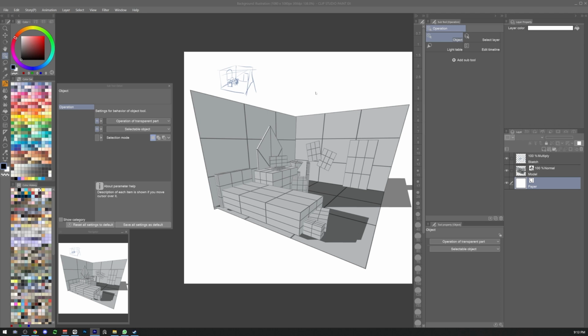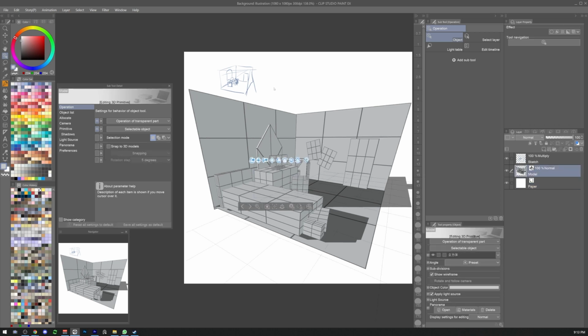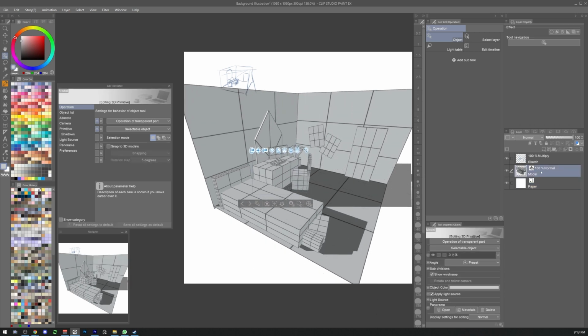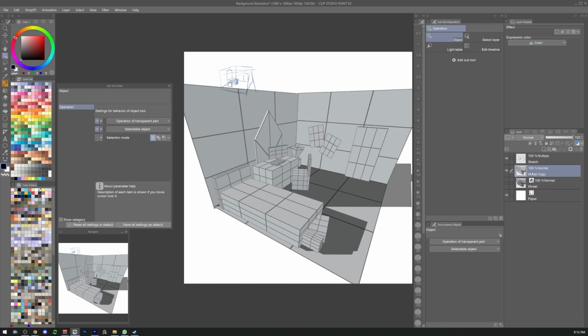When we will finally have our scene ready, camera placed, and everything is where it's supposed to be, we can create a backup and then rasterize the duplicate layer, right-clicking on it in the layer window and then choosing rasterize. This will turn the 3D layer into a raster layer that will behave like a picture.